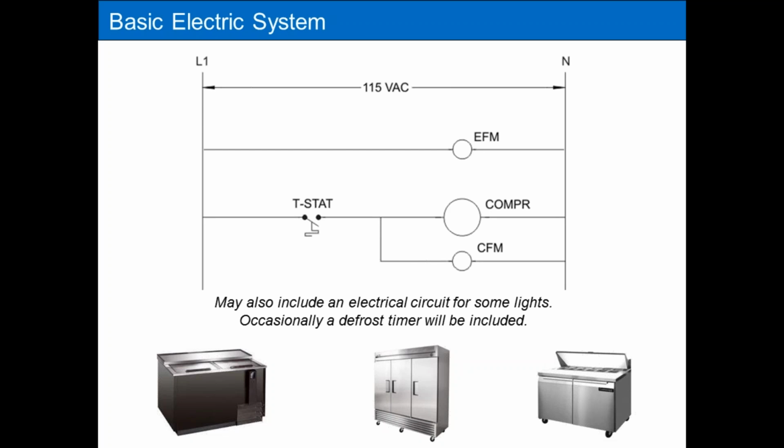during a defrost. It doesn't cycle on and off when the case gets to temperature. It runs all the time. If you look on the wiring diagram, the sample one I have on the screen, you'll see that there is no switching in the evaporator fan motor circuit.